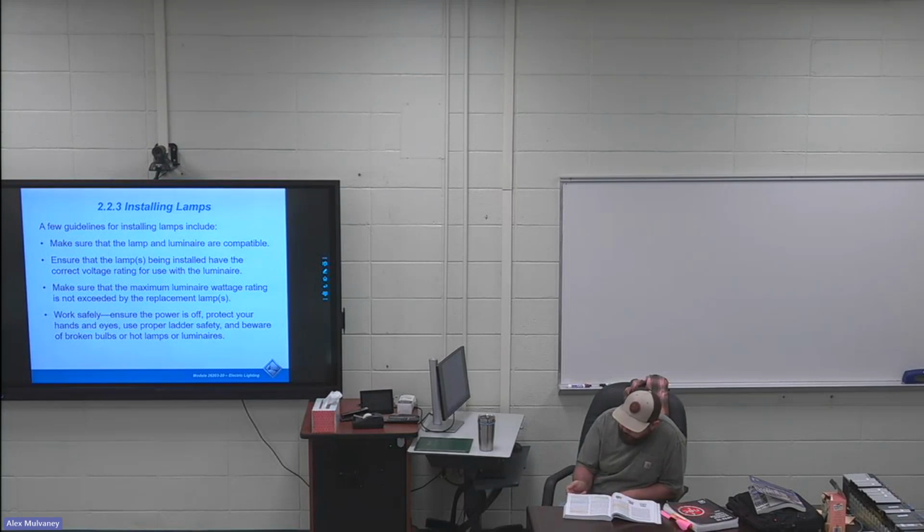They start off with bullet points with different names for these ballasts. If you flip over to page 20, second bullet point, first sentence is highlighted. The electronic program start ballast. These ballasts offer the longest lamp life due to minimal cathode damage when starting, and nearly as great energy savings as instant start ballast due to reduced cathode heat. Make sure you have that highlighted.